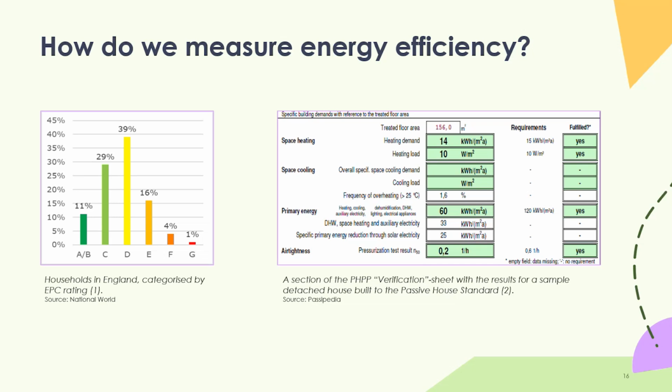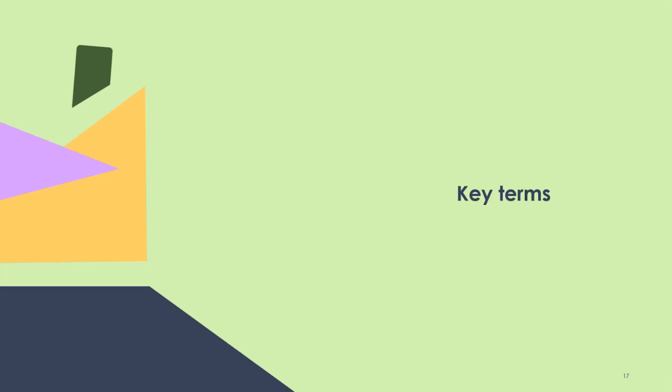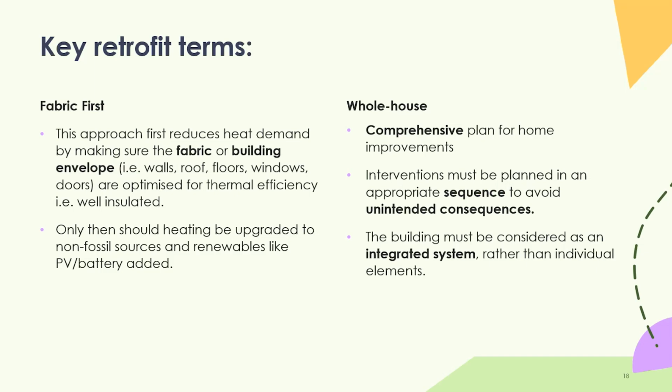And most of our homes in the UK are around this D band level or worse, so maybe 2/3 at D band or lower. And that's of course what these warm homes programs are really designed to tackle, trying to get them out of those D, E, Fs and Gs and up towards C and above, with SAP C being regarded as a reasonably solid base level for retrofit. As I say, there's a lot of nuance to SAP and EPCs and the inaccuracies and what they favor in the modeling and the generation of that rating. But yeah, that's a whole other rabbit hole that we don't quite have time to get into right now.